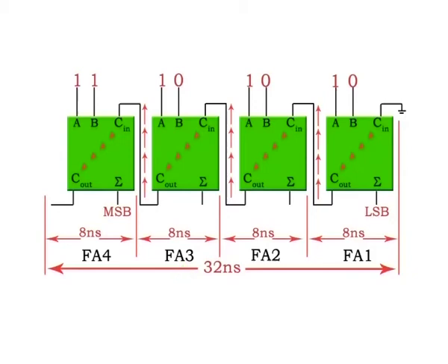As you can see in the figure, the input carry to the least significant stage has to ripple through all the adders before a final sum is produced. The cumulative delay through all the adder stages is a worst case addition time. The total delay can vary depending on the carry bit produced by each full adder.